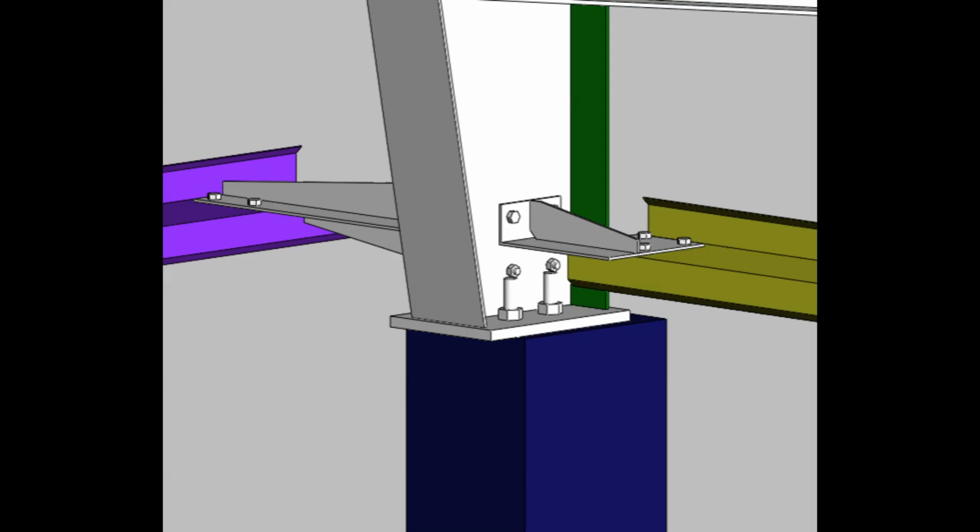Finally, this close-up view shows a steel column base connection together with diagonal support members connected on both sides. At the bottom, the steel column is supported on a base plate secured by anchor bolts. The inclined support members are connected to the main framing through bolted connection plates. This arrangement demonstrates how different structural components can come together around the lower portion of the frame.